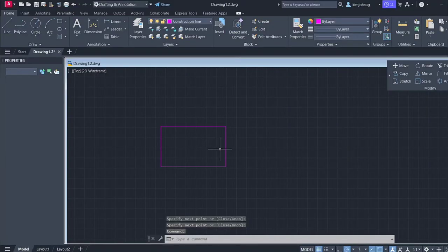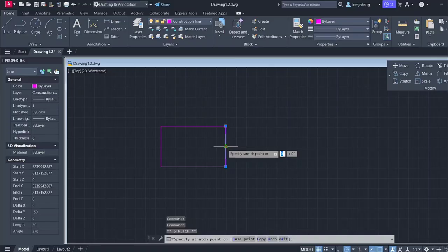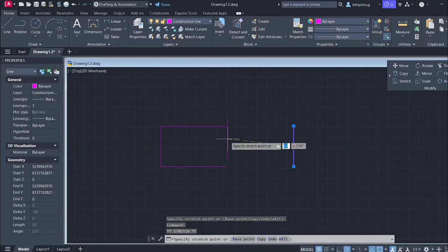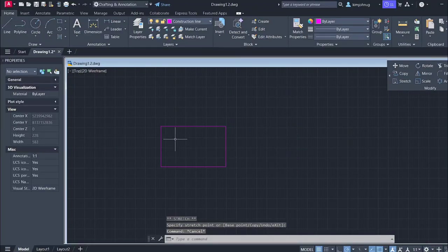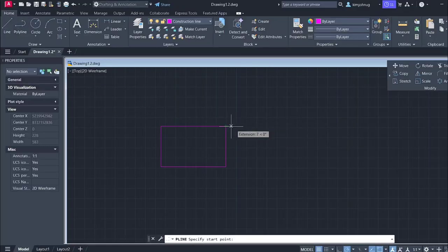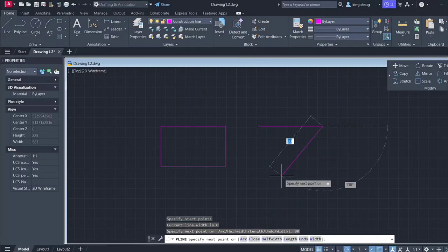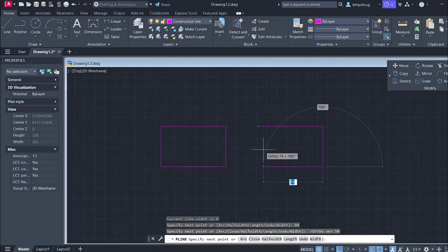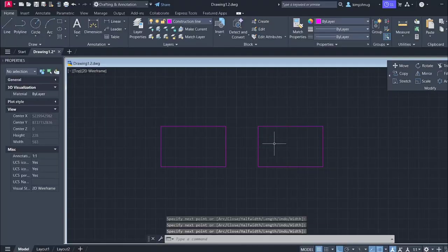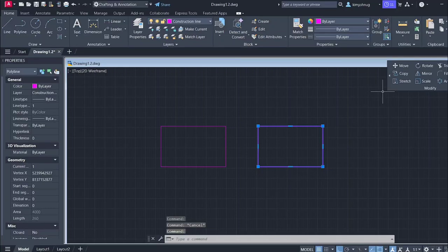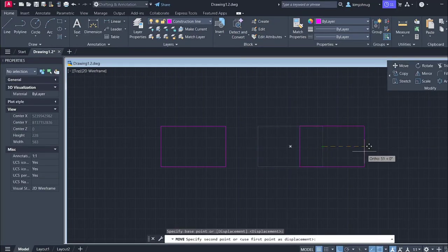Now I realize that all these lines are not joined, meaning I can move this line, I can move it back. You see? So let's use now polyline to see the difference, to do the same rectangle. So it is 80. Some people prefer to use the ortho mode for this by 50. Do the same trick and then you join. So for the polyline, it joins the figure immediately. What does that mean? Meaning I can't move the line like the way I did last time. I would move the entire figure.